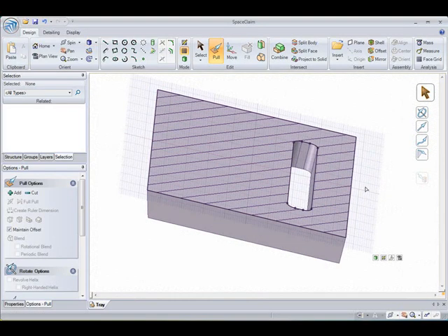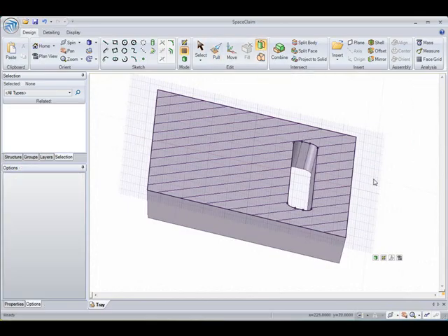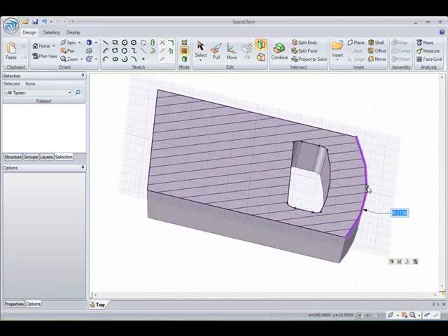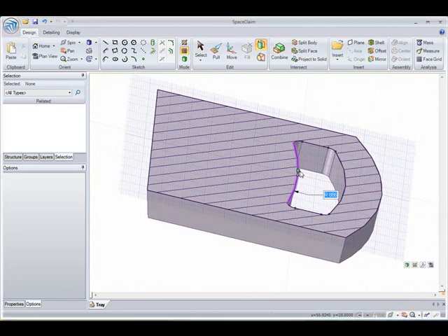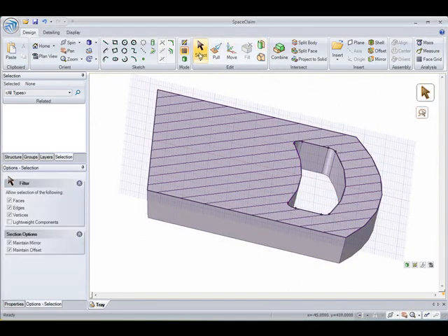But now let's add some more contour, and we'll do that with our bend tool, which allows me to bend a straight line in a section or a sketch into a curved line. So I'll bend it out and I'll type in 600. And notice that when I bend out the outer one, the offset wall bends as well. And I'll do the same to our inner wall and bend that 600 too.